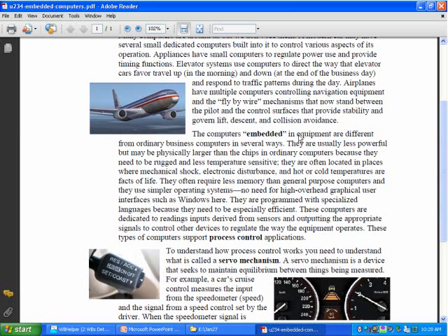The stealth fighter is like this. It's not really very stable. It has to be controlled by a computer that senses things and controls those surfaces very fast, almost like an automatic pilot, except it's controlling the stability of the airplane. Anyway, fly-by-wire means that the pilot is one input to a computer, and the computer's output is the thing that determines how things are set and makes the airplane fly.